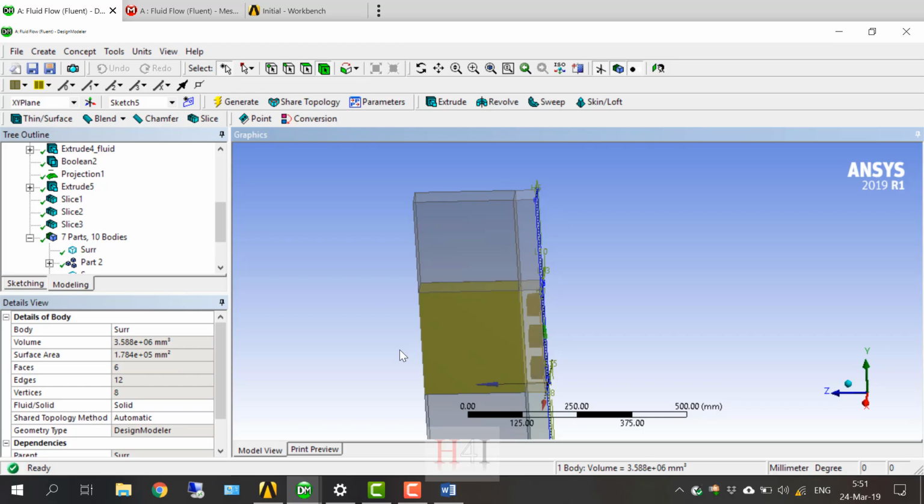But it's available to use multizone? Yes, it is. If you have no problem with the mesh having the same size on the whole region, okay. But now I can make the mesh a little bigger at the end, and smaller near the heatsink. So using bias is good. It will save some elements and can decrease the elements further.